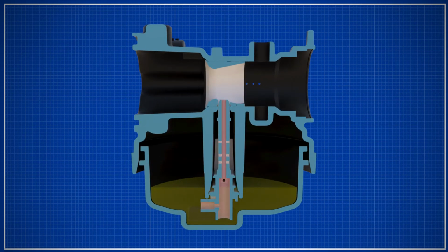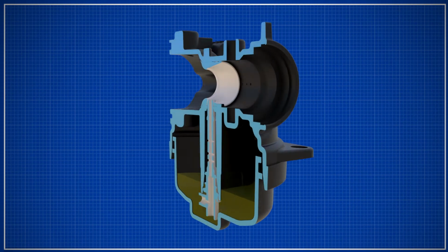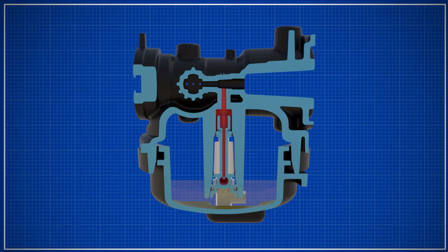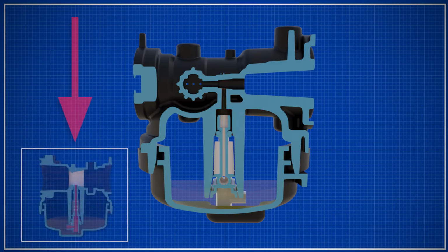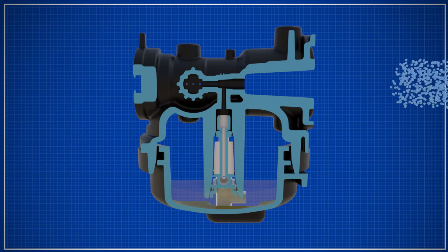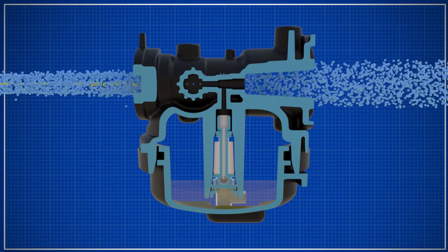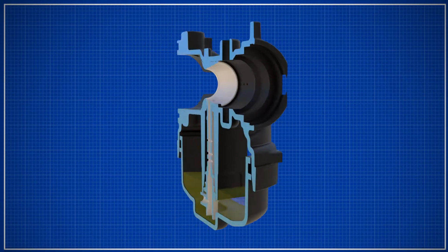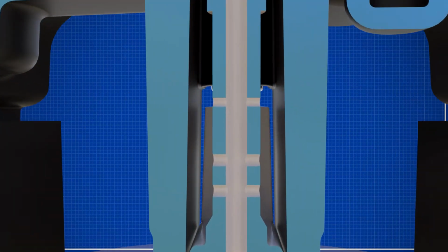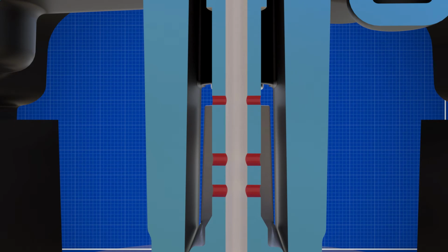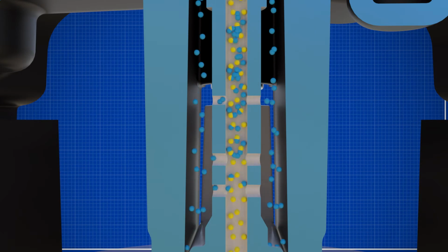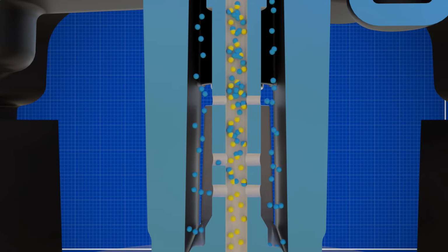Fuel supply circuits for high and low speed are added to the carburetor. The high-speed circuit is the main nozzle on this carburetor. The low-speed circuit passageway is built into the center leg of the body and moves fuel to a chamber. When you look at the main nozzle, notice the smaller holes around the outer diameter of this tube. These holes work together with the high-speed air bleed passageway. The idle circuit has an air bleed as well.